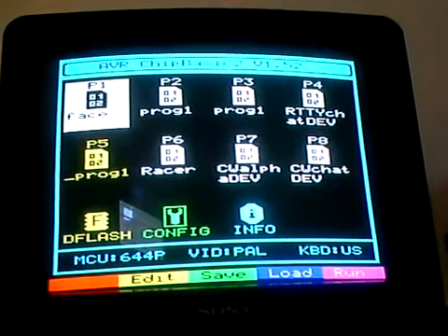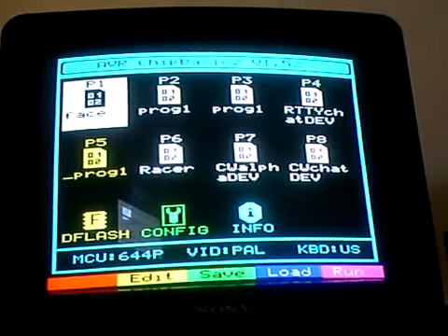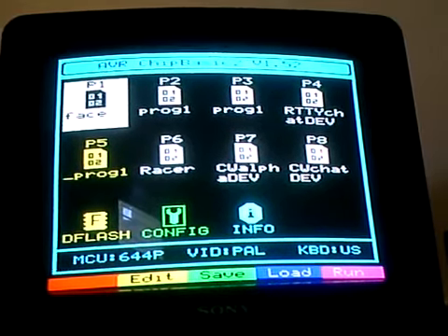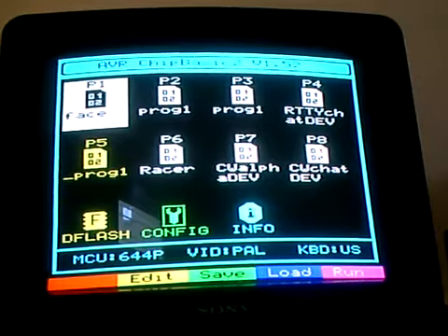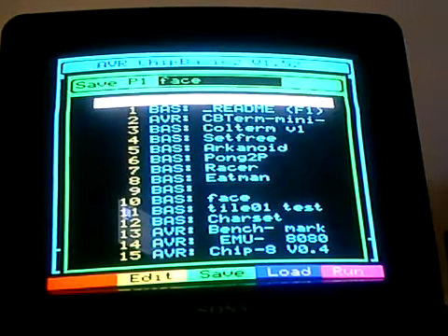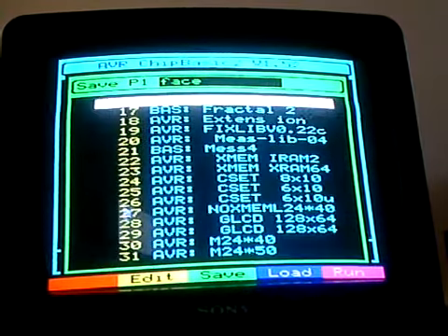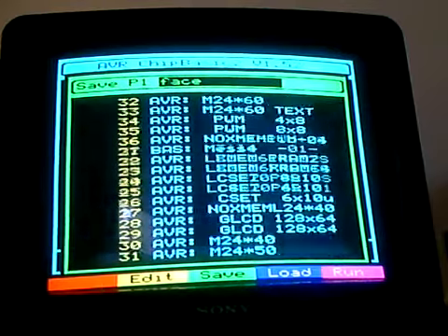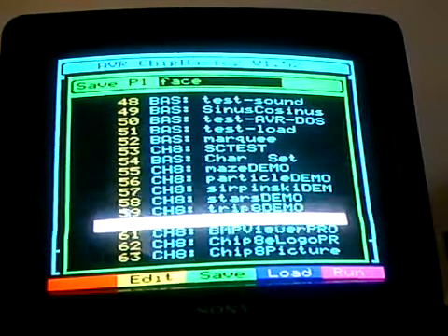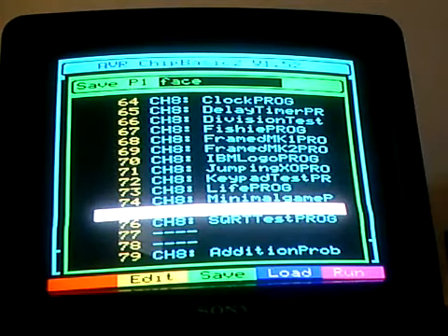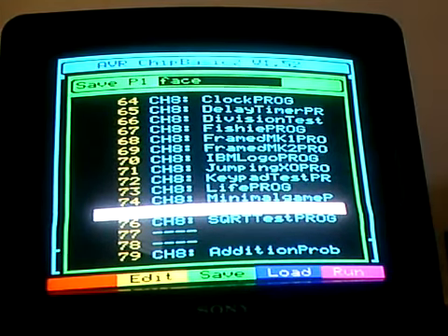Also, if you want to save a program into the data flash, you click the save menu, which is F2, and again you will be guided to the data flash here, and you can choose a free position to save your program. When you already have a program stored in this position, there's a warning pop-up dialog which asks if you want to overwrite the current program.